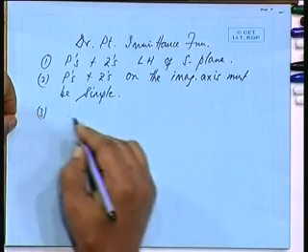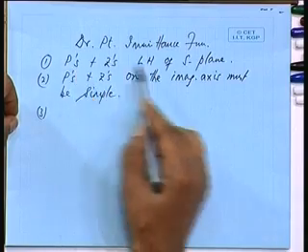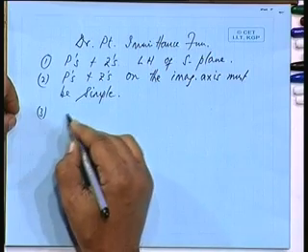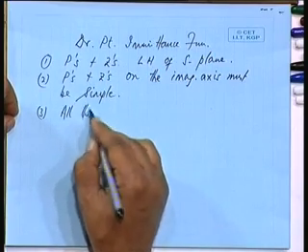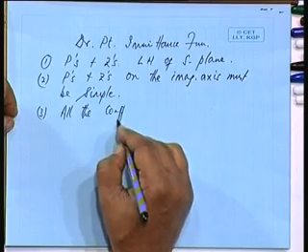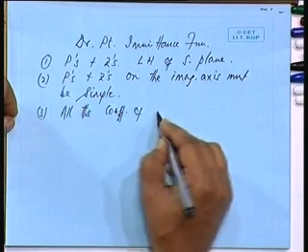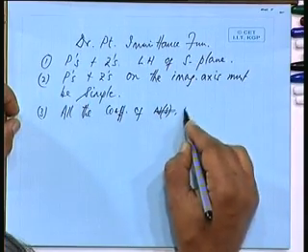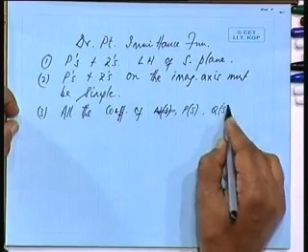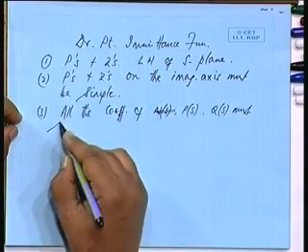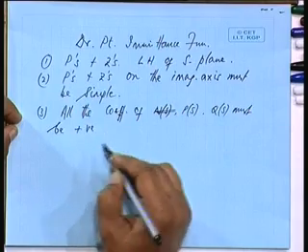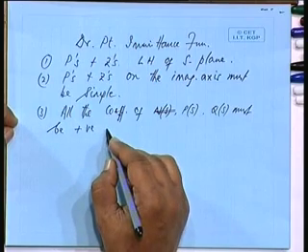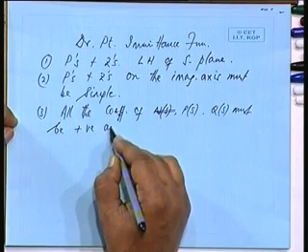And then to ensure that poles and zeros lie in the left half of S plane, actually all the coefficients of the polynomials, all the coefficients of numerator and denominator polynomials, we were using P(s) and Q(s), okay. P(s) and Q(s) must be positive, all the coefficients of P(s) and Q(s) must be positive, okay, and real.